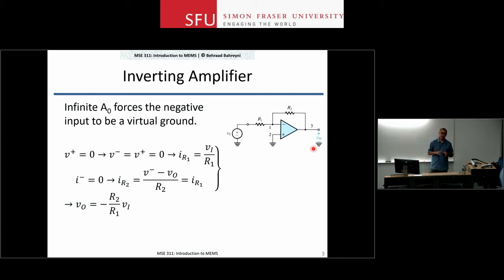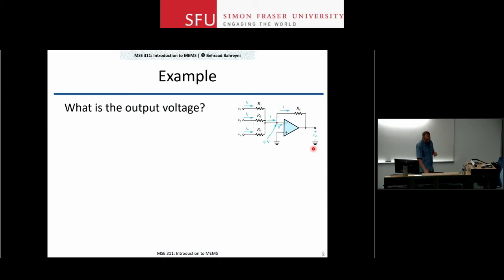Practically, you want to choose R1 and R2 in the range of, let's say, about 100 ohms to maybe 100 kilo ohms. That's a reasonable range for these resistors. And that gives you a very wide range of values for the achievable gain and input resistance. Here is an alternative or a modification to that circuit.